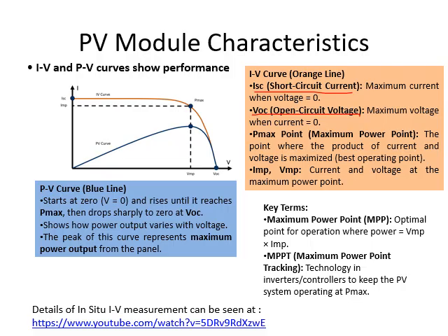On the IV diagram, your ISC is the highest possible current at 0 voltage, the short circuit, and the IV curve follows like this, and VOC, open circuit voltage, is the highest voltage. In between it works, and the actual PV curve will go like this.